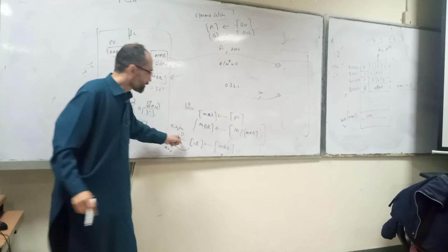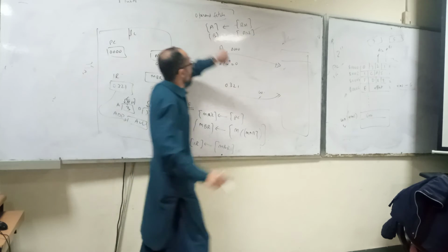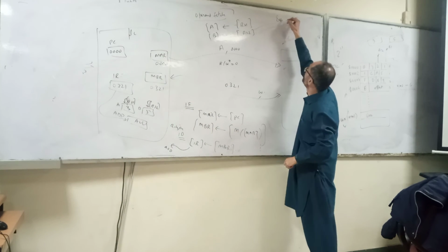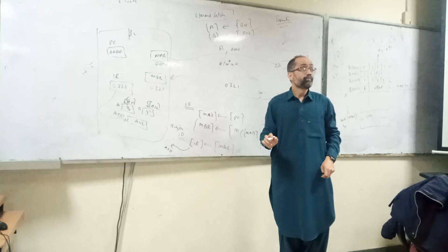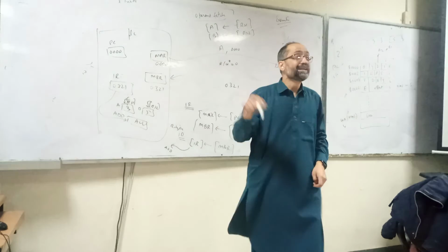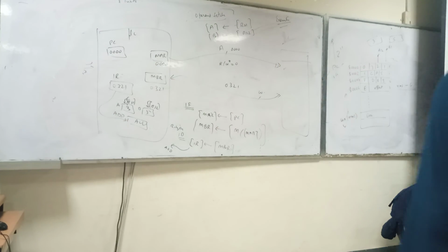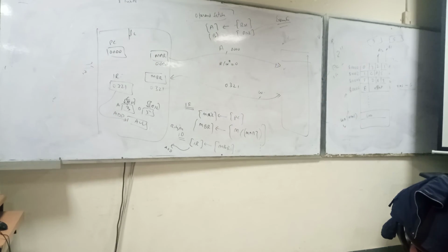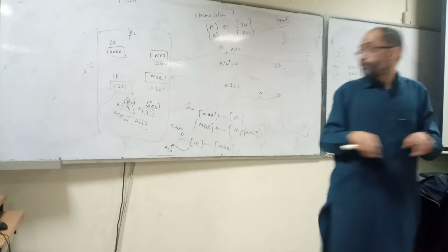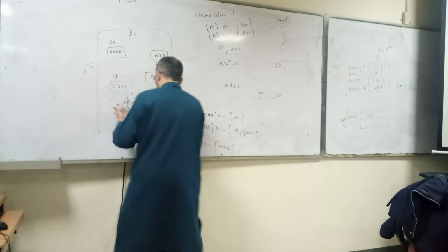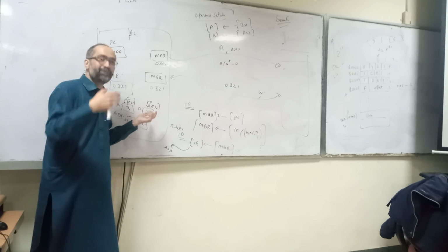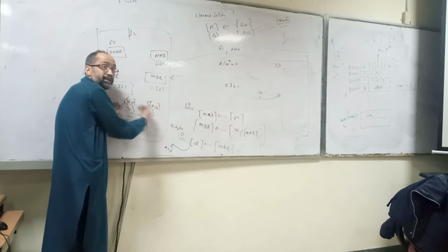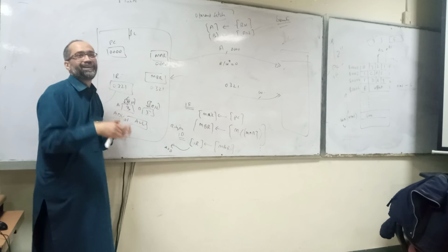Instruction fetch stage, instruction decode stage, operand fetch stage. Now we will execute this instruction. In this case, A and B are internal registers within the microprocessor. They are not visible to the programmer. If you want to perform these operations, you need to load this data, so you need some latches, flip-flops, or buffers. These are internal registers that are not visible.